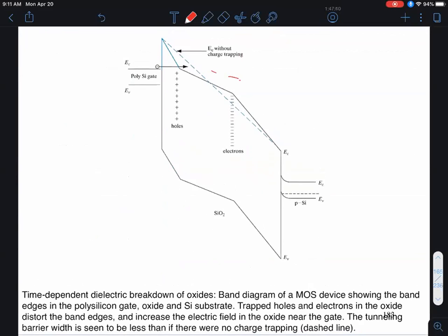Same in hafnium oxide, it's very, very low because these dielectrics are amorphous materials, and typically in amorphous systems, you have low mobilities, okay? Because the mobilities are so low, when these electrons tunnel into the material, they gain kinetic energy, they can cause impact ionization within the oxide, exciting electrons from the valence band of the oxide to the conduction band. In the process, they leave behind holes, and you create secondary electrons.